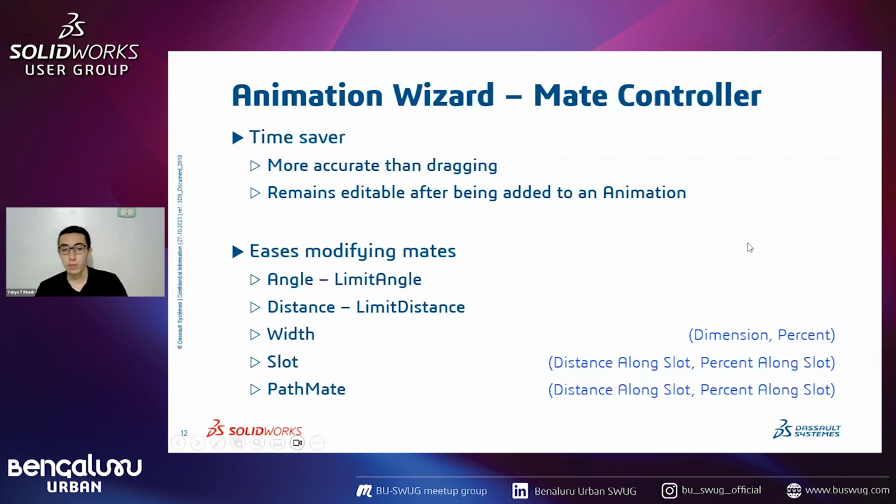So when it comes to mate controllers, the supported mates that we've got are these mates listed down here. So angle mates and limit angle mates, distance mate and limit distance mate. And we've also got the width mate, the slot mate, and the path mate. But in these 3 mates, we must choose something that is numerically controlled. So for